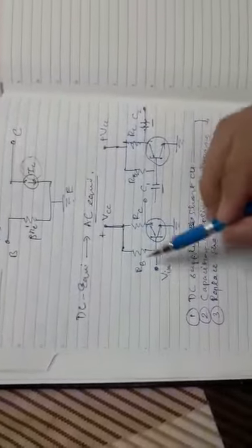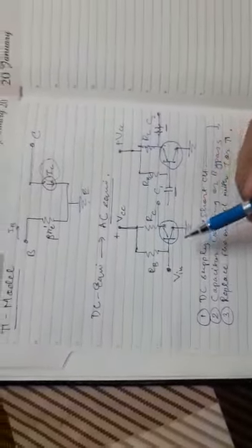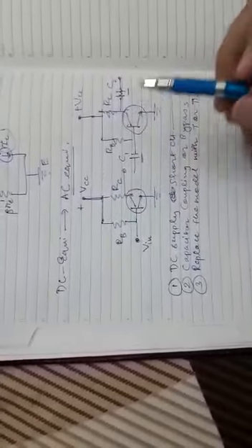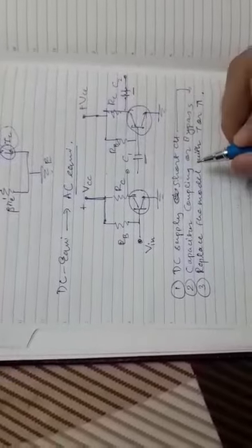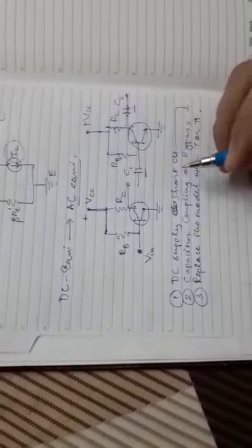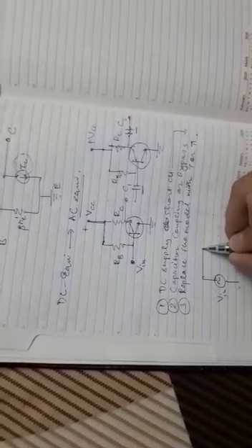So the first thing we need to do in this circuit is take the base resistance and collector resistance to simplify the circuit. The base resistance will be like this with the supply, that this is our input supply V in. With this input supply, the base resistance will be in parallel combination.